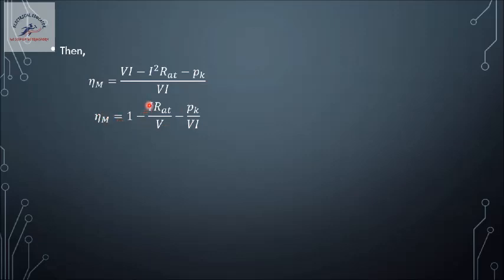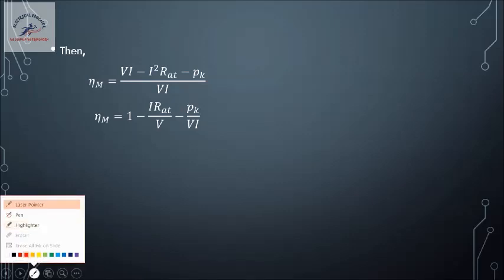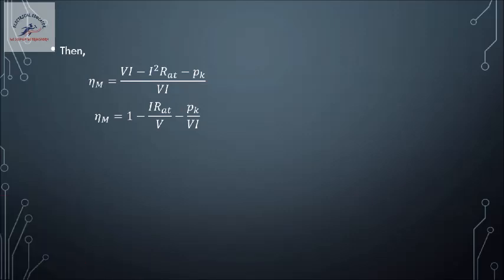In this particular equation we can observe that the efficiency depends on the line current, and line current increases with the load. So as the load varies, the efficiency will also vary. Now we have seen the efficiency curve for various electrical machines, maybe a transformer or DC generator, whatever it is.